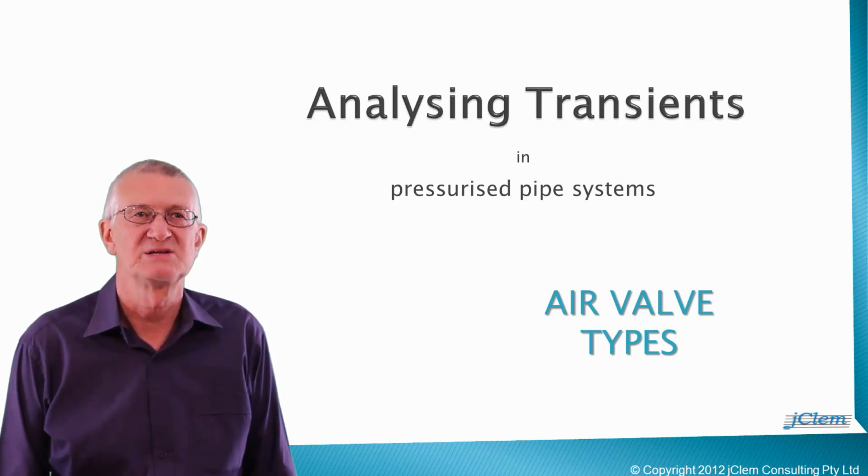WATAM users need to understand these differences and match their selection of air valve type to their specific project requirements. Users have often asked why so-called anti-shock air valves give slightly worse simulated surge results. It is because both types of valves close fully and instantly at some point in their operating sequence. One type does this with air trapped in the pipe, and the other type, marketed as anti-shock, does not.